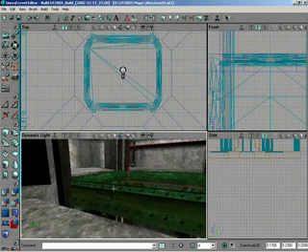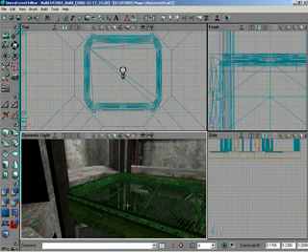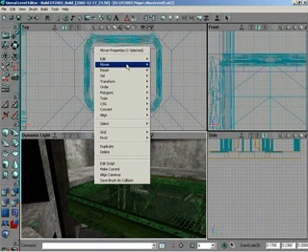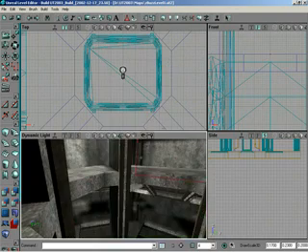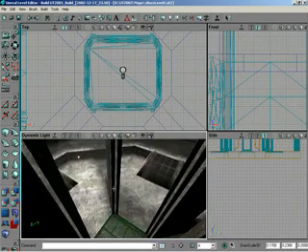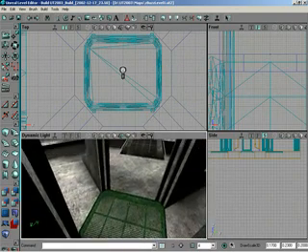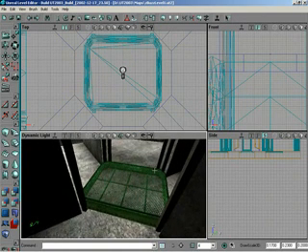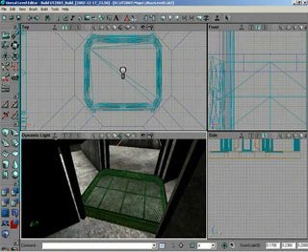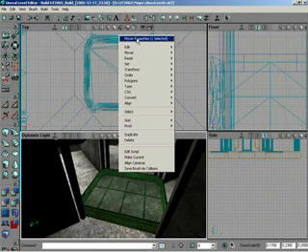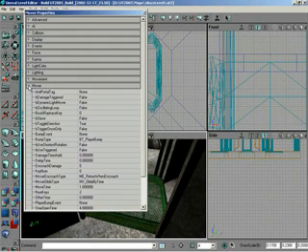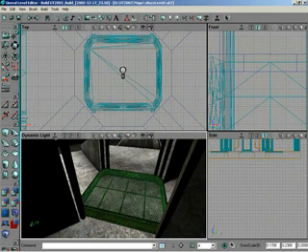So that's key 1, meaning that after it starts moving, this is where it's trying to move to. So let me right-click on that and make sure we set it back to key 0 before we play, so that we make sure it starts on key 0. Okay, very good. One last thing, it's set to move in 1 second, which is a little bit fast to get all the way up there. So I want to change one property on it by right-clicking on it, bringing up its mover properties, under mover, setting move time to 2. Still kind of fast, but not as fast. So let me close that out, and that's all we need to do.